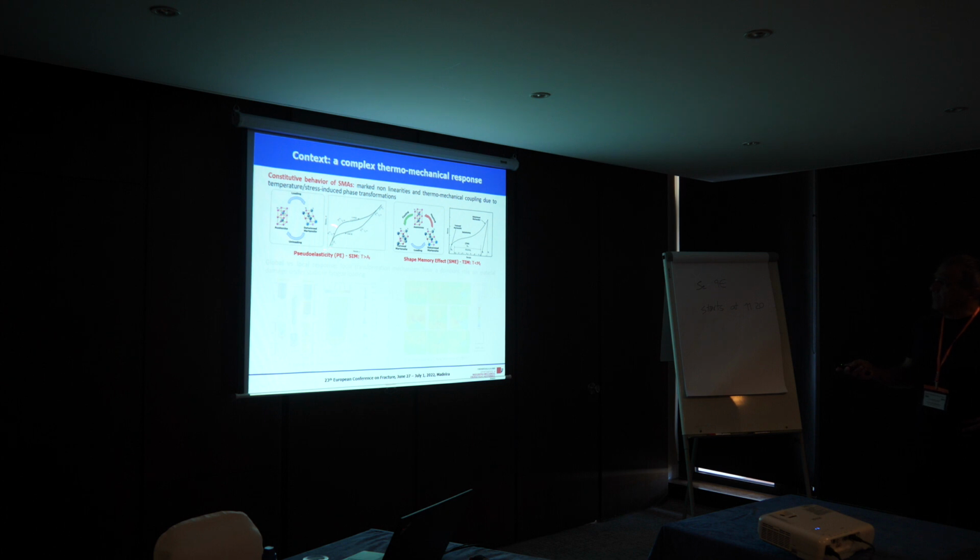It means that if you start from the austenitic structure, the austenite is transformed into martensite on loading, and this transformation is fully reversible on unloading, resulting in a very large strain recovery.